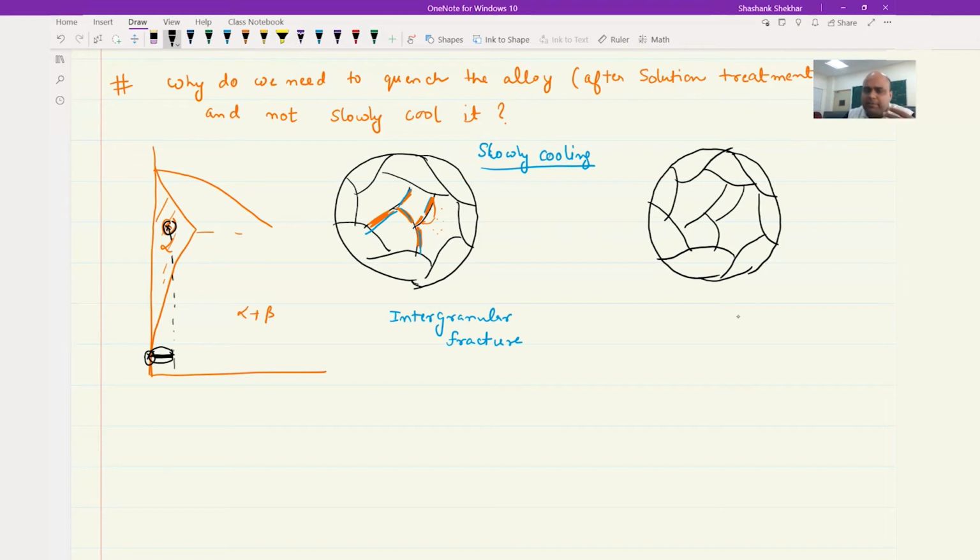You are not at very high temperature when you age it, but you are giving some driving force so that atoms can move. Atoms want to come out quickly and achieve equilibrium, right? So what will happen? They will start forming precipitates inside itself. Obviously, you are going to observe some precipitates also at the grain boundaries. No one is denying that. But apart from the grain boundaries, you are also going to observe precipitates in the interior, inside the grain.